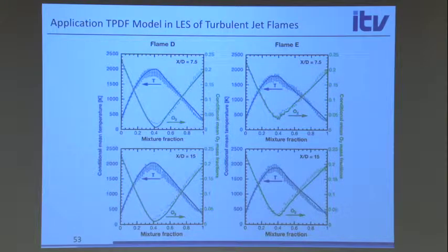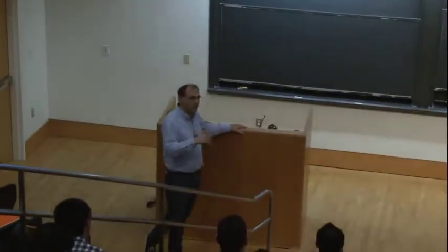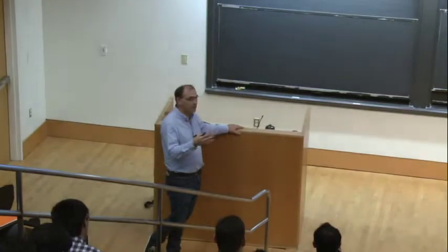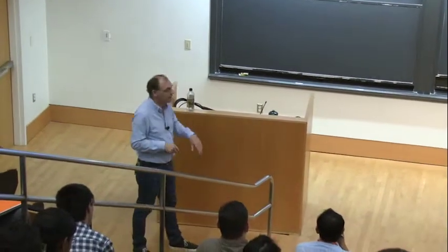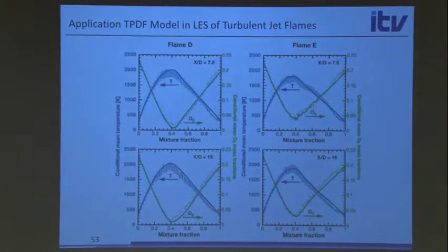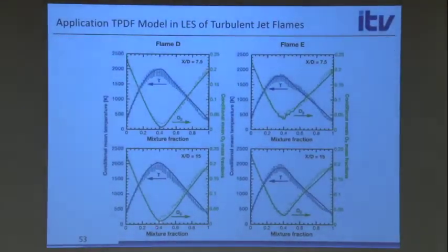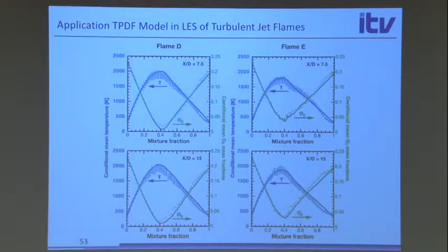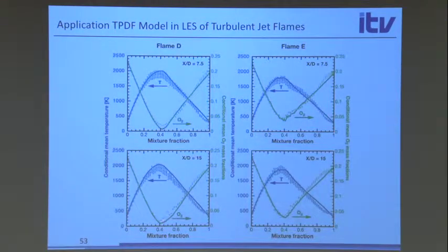The laser diagnostic people want to prevent the formation of PAHs, which would interfere with their LIF measurements, and so they put some oxygen here in the fuel. But you see here, the oxygen for stoichiometric conditions should go to zero. It doesn't quite go to zero, and that is because of finite rate chemistry effects. That is because the chemistry is not infinitely fast.